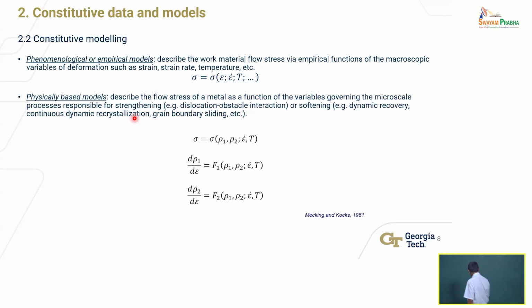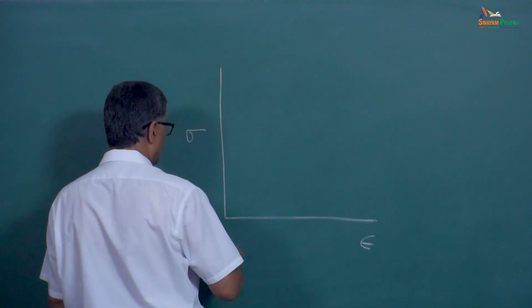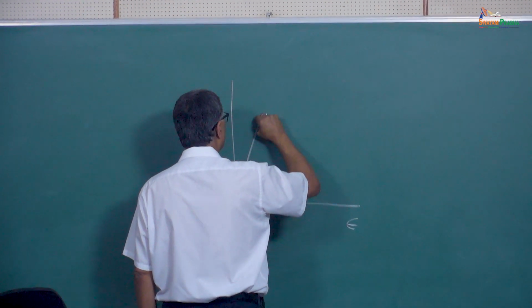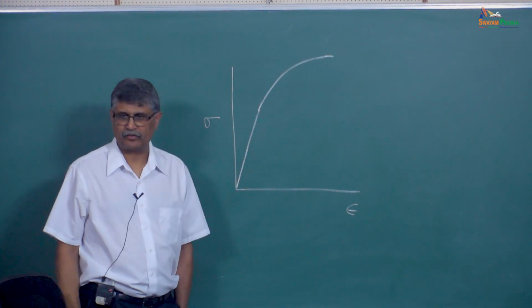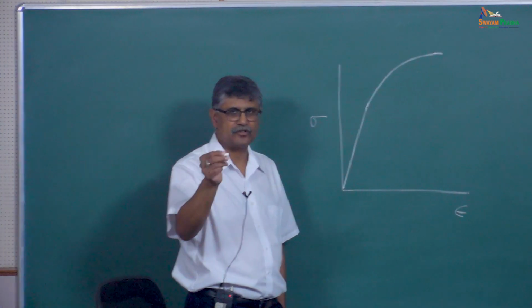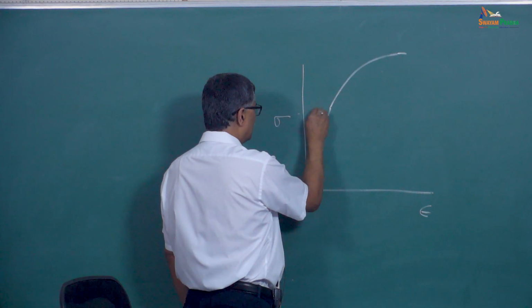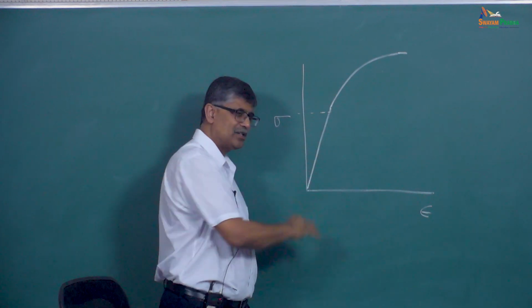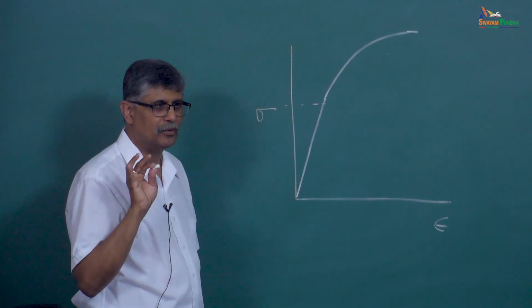Strengthening, and this is maybe where I will use the green board. So something like this. You're all familiar with stress strain curves that you may get from a tension test or from a compression test, right? Let's say this is the elastic limit. Now, for machining, the elastic region is really not important unless you're trying to predict residual stresses and so forth. Only then it's useful.